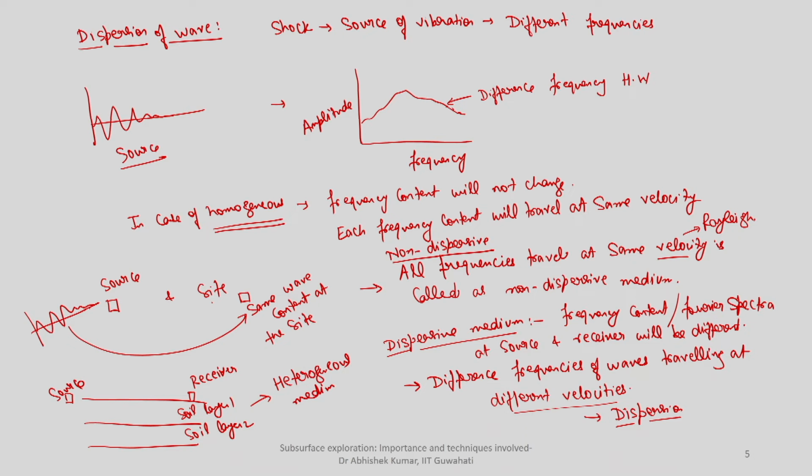So, in surface wave analysis, or precisely Rayleigh wave analysis, we are interested to understand the dispersive characteristics of the medium, which has been seen based on source frequency content and based on receiver frequency content. And if we are able to interpret this dispersive characteristic, we want to find out the corresponding medium which is inducing this kind of dispersive characteristic to your wave content.